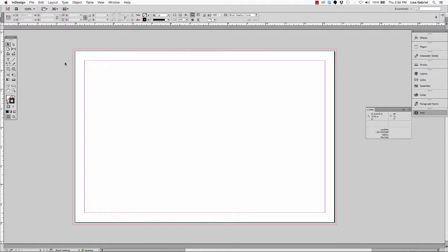So you're going to grab, basically I just sized that down so that you can see what I'm doing. When you grab that guide out of the ruler, you want to kind of stay in the clipboard region instead of in the page region, because you see the difference between the guide. When you're in the page region, it cuts off the guide at the trim edge. When you're in the clipboard region, your guide extends all the way to the very top and bottom. And we're going to need those guides in our clipboard area when we go to draw our fold lines. So it's important that you make sure that you pull that guide out in the clipboard area. So I'm going to drag this until I get to 3.375.